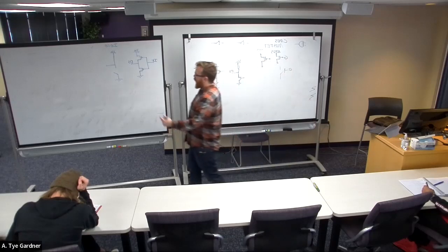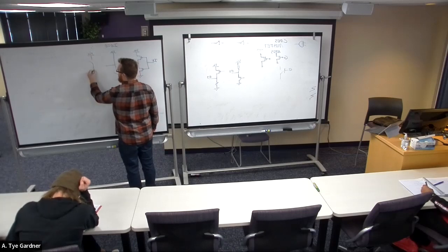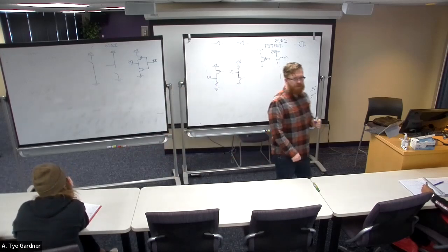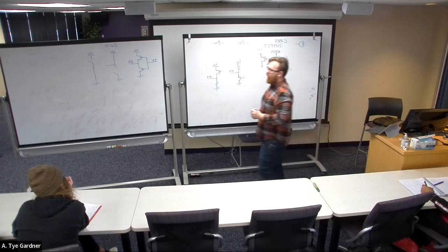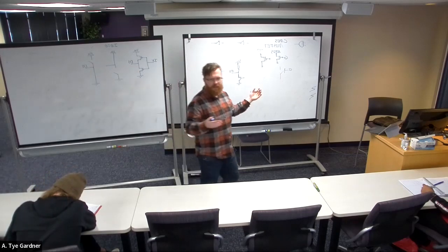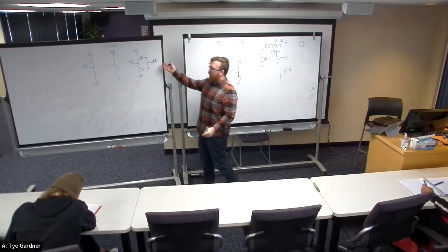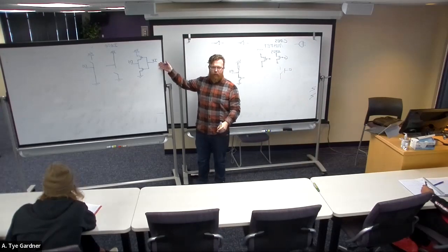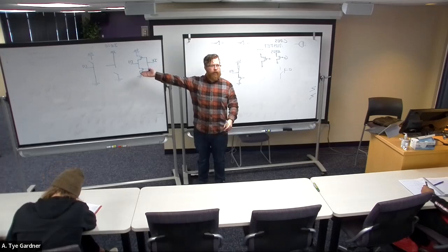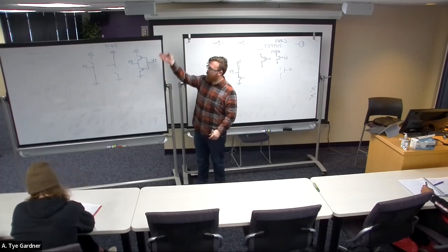If I put a 1, the PMOS device turns off, it opens, but the NMOS device closes. So I put in a 1, and now my digital signal is still in the same spot, but it's a 0. It's connected to ground. And so as long as we don't do something weird with the input and put it somewhere in the middle where they're both half open, then as long as we put a 0 or a 1 in, in neither one of those cases does any current flow, right? There's no path in either case between power and ground.